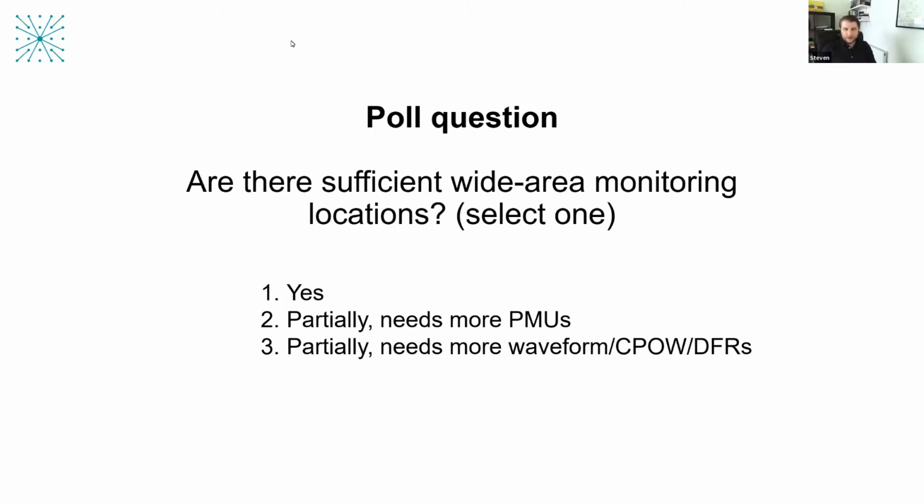Yeah, definitely. Wind farms bring together so many important aspects that deserve a considerable amount of monitoring. As you said, you have multiple generators relatively close together on the same network, with converter interfaces, so they must be injecting harmonics. So sooner or later there might be a resonance issue in the network, because obviously the wind is intermittent, so certain generators may be out of service, so the network impedances will shift over time. Particularly if there's an HVDC link back to the shore, if the export cable is HVDC, then that wind farm is effectively its own little AC network, which has to be controlled. So there's lots of interesting things going on in wind farms, and that's why we think this continuous point-on-wave monitoring is particularly applicable there.